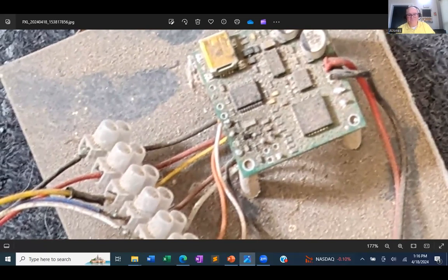But I'll dig up my servo tester. Yeah, the problem I had: I got one of the linear actuators, and I did put out the extra money to get the feedback. But when I tried to run it, since it had 5 wires all bundled in a cable, and I was trying to use a PWM to drive the motor, that created enough noise into my feedback that it wasn't usable for what I was doing.